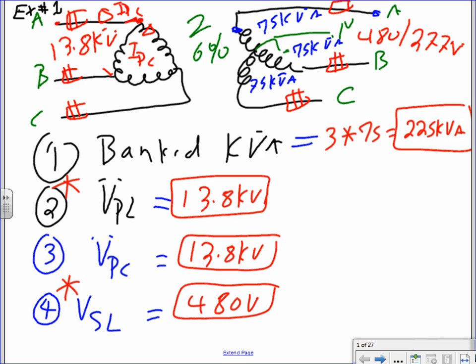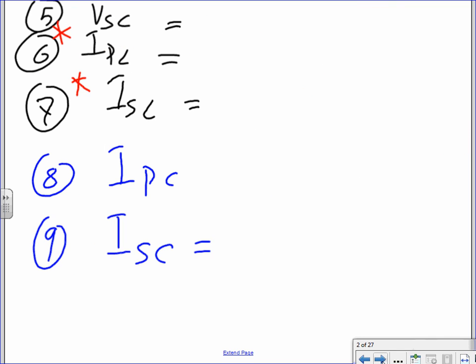Voltage in the secondary, for you guys, you skip it to the right side on that sheet I gave you. Okay, so that's V secondary. How about V secondary coil? Here's the coil. Can you guys see the coil between the neutral and the phase? What's the voltage between the neutral and the phase? You guys know that, the lower voltage, 277, right? Okay, so the next one is V secondary coil. That will be 277 volt. Done. All right, now I primary line.